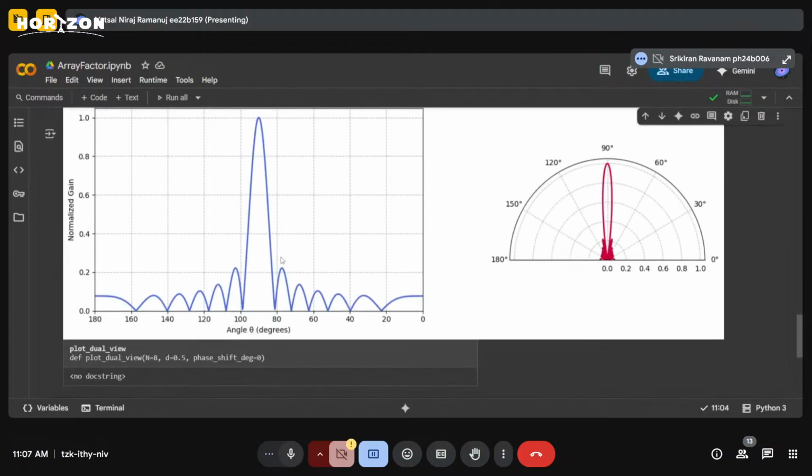One consequence you can see very clearly from the right hand side graph is that the half power beam width, or the width of the lobe, has shrunk down a lot. So in a sense, our directivity has increased so much from the 5 antenna case. Antenna arrays used for radio astronomy sometimes use hundreds of antennas.